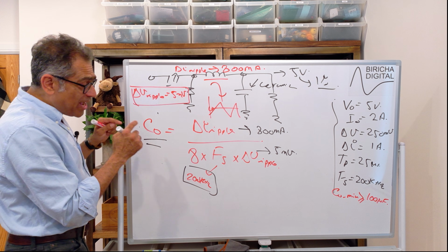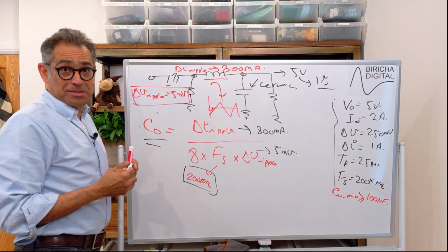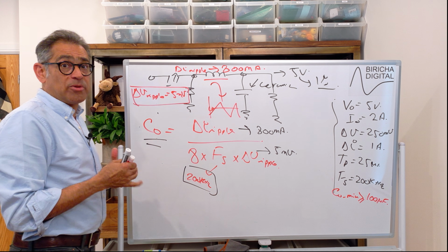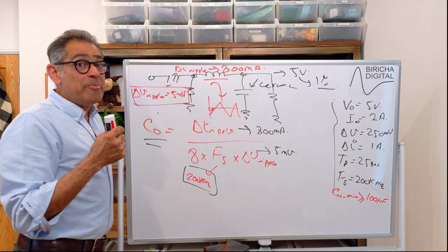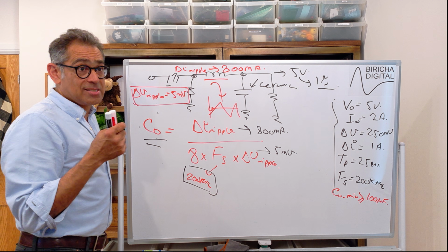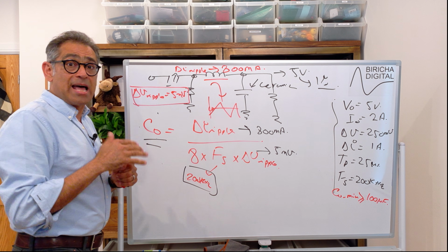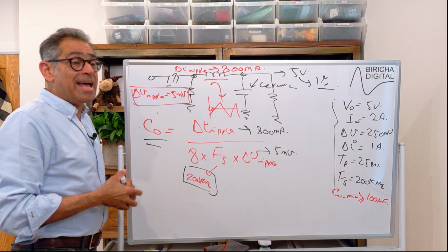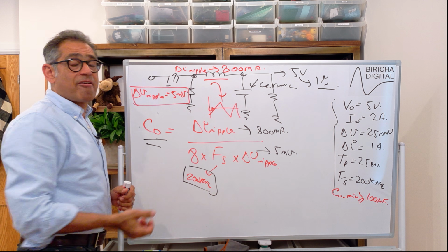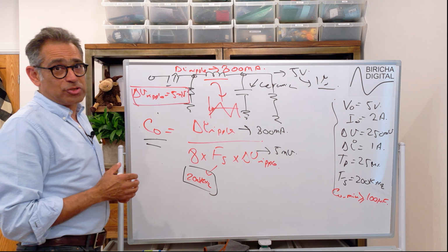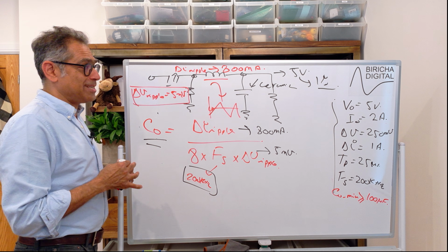And whichever value of these two is the bigger one is the amount of capacitance that you need for a power supply that has got ceramic capacitors on the output. Please remember that ceramic capacitors have got something called a DC bias loss. Their value really collapses as you increase the DC voltage on it. Allow yourself a factor 2. So if you're calculating 100 microfarad, add an extra 100 microfarad on top, and 200 microfarad is the amount of capacitance that you need. And there we go.